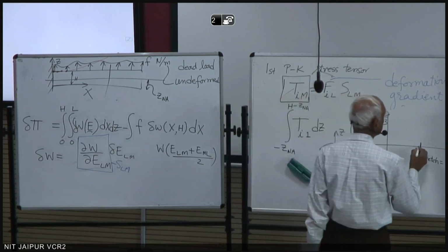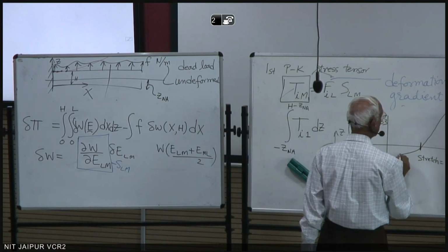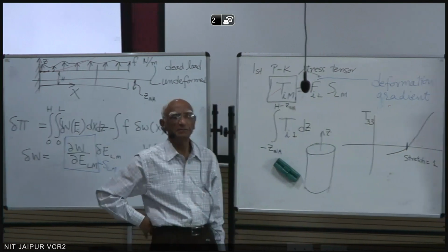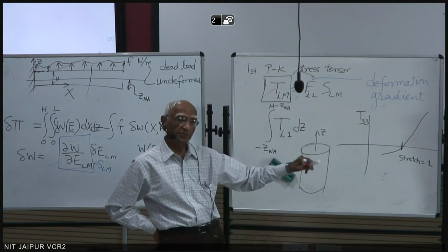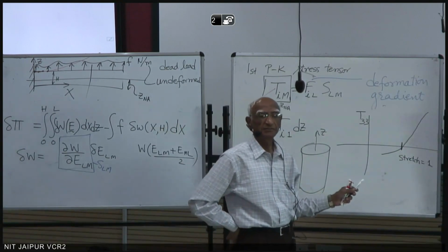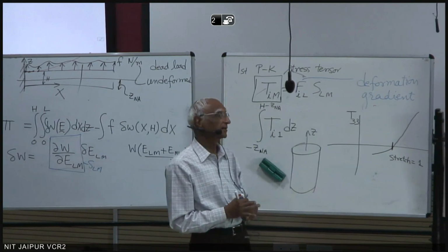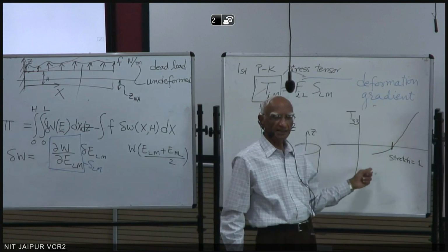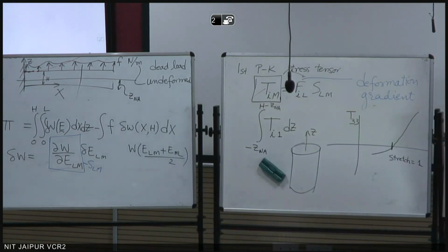So the response you get is not symmetrical in tension and compression. So you can say this is a weakness of this material model. Unless you have a material that has different response in tension and compression, this is not a good representation of that material.